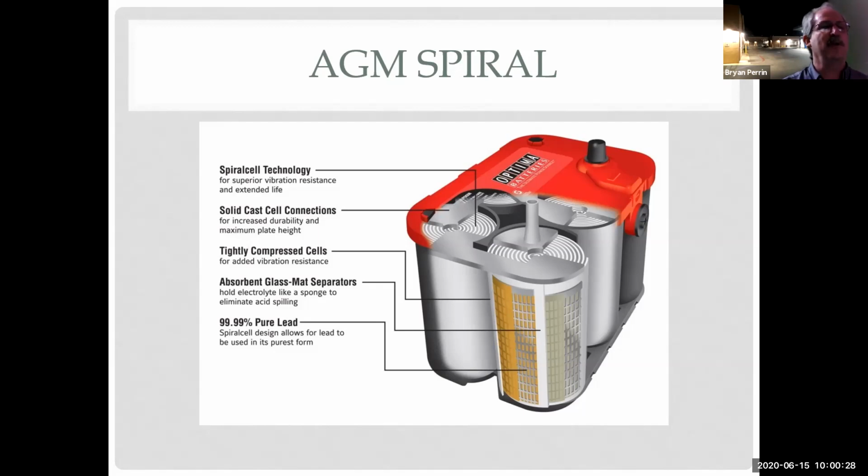And unfortunately, if you go into XYZ Auto Parts store, this is the battery they try to sell you because it's the best. And then you keep replacing it every 1 or 2 years and you don't understand why. Square peg, round hole. Great technology, but again, charging precautions. I can't use any battery charger on it. I need to use an AGM charger. My car thinks it has a lead acid battery. It's going to try to charge this like a lead acid battery. It's going to cook it. It's going to overheat it. It's going to destroy it.